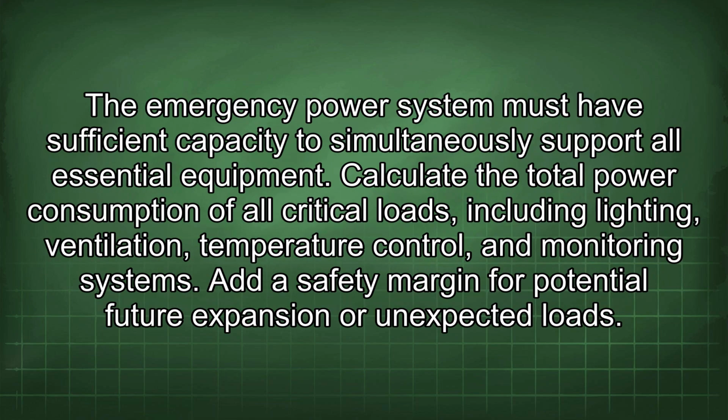The emergency power system must have sufficient capacity to simultaneously support all essential equipment. Calculate the total power consumption of all critical loads, including lighting, ventilation, temperature control, and monitoring systems. Add a safety margin for potential future expansion or unexpected loads.